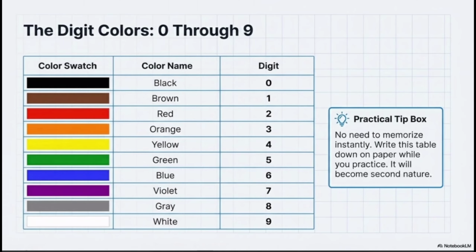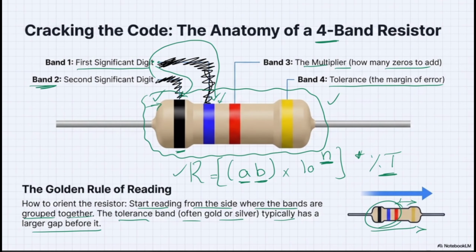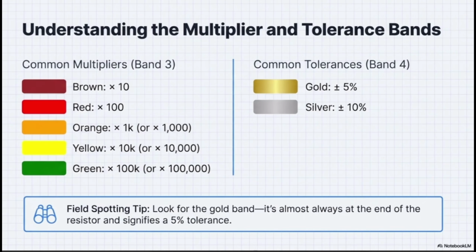So right now, let's talk about the colors. Each color means something, and it doesn't necessarily mean that you have to memorize it. You can have it as a reference, but right now, black means 0, brown means 1, until the end. Why do we use that? We are going to put it inside this specific formula that I was talking about. By putting it there, you make sure that you can read your resistance without even measuring it, by color coding. So let's talk about the case.